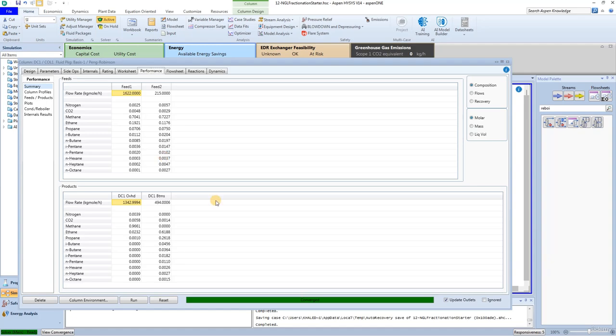Although the column has converged, it's not always practical to use flow rate specifications to satisfy the required degrees of freedom. These types of specifications are strongly dependent on feed properties and can result in columns which are difficult to converge or that produce undesirable product streams when the column feed conditions change. A more flexible approach is to specify either component fractions or component recoveries for the column product stream.